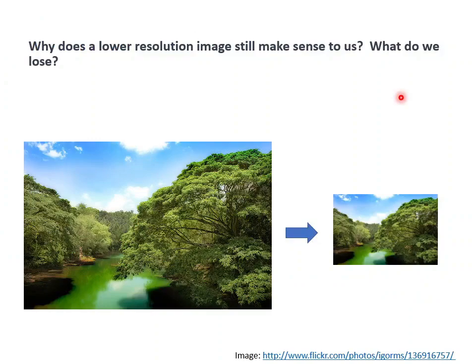So let's go back here. Now you know when we generate the low resolution image, we lose the high frequency signal, and if we want to prevent or reduce the aliasing problem, we can apply a low pass filter. In particular, Gaussian is the widely used one to combine those high frequency signals together and preserve them in the low resolution image. So there is a term called image pyramid, like this.